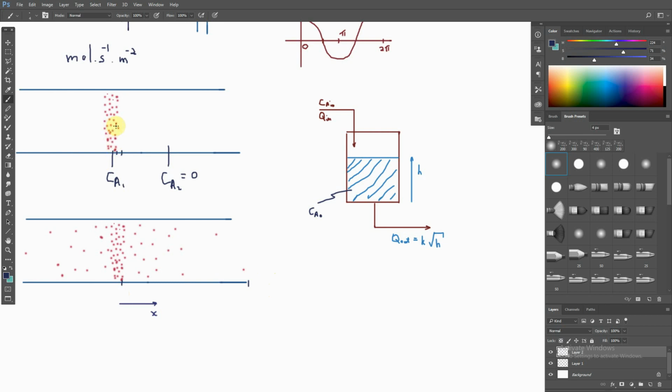And we can imagine then that the diffusion flux away from this point is going to be much higher here than compared with here. Here, even as you diffuse away from this higher concentration zone, there's still a component A here which may be perhaps repulsing your effort to diffuse in this direction. So that's going to slow down your transfer rate. So there's a greater space over which the same difference is distributed, and so your diffusion flux is expected to be lower in this case. So we can see that the expected flux is going to be proportional to the difference in the concentrations. So the concentration at one value of x minus another value of x, a value at a different x, and we'll call that delta x.